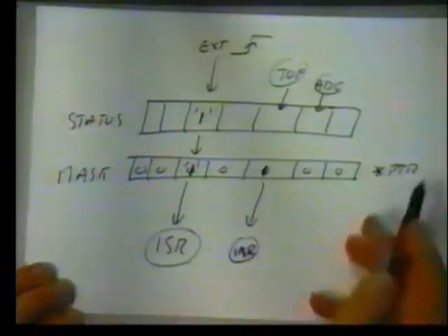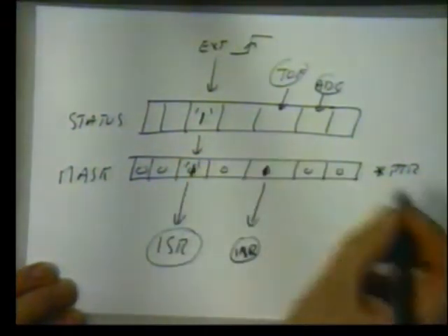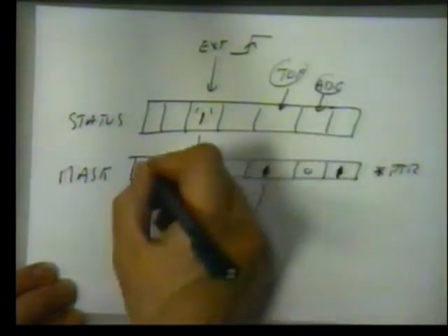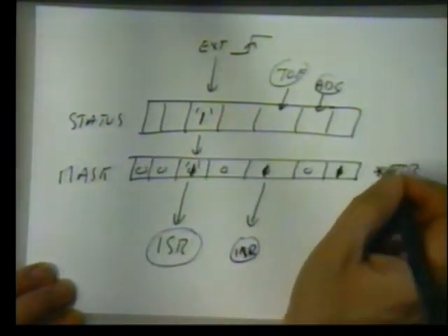It's your job as the programmer to enable the relevant interrupts that you require for your particular real-time routine. Whatever it is, you've got to do it. So you have to go to the interrupt mask if you want the external interrupt, the timer interrupt, the serial interrupt. You have to set up the mask to allow them to happen.